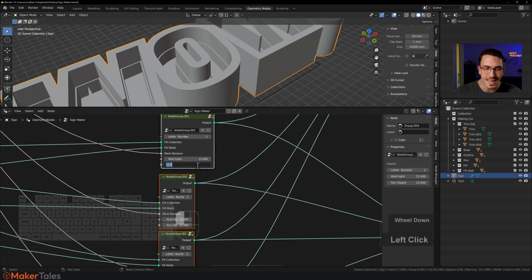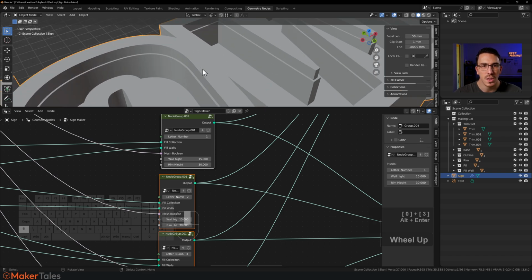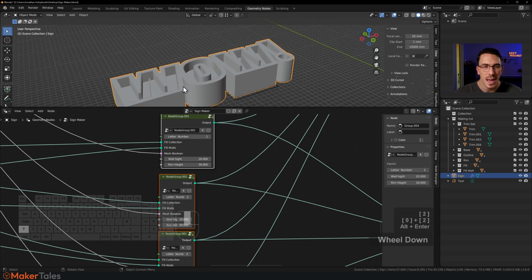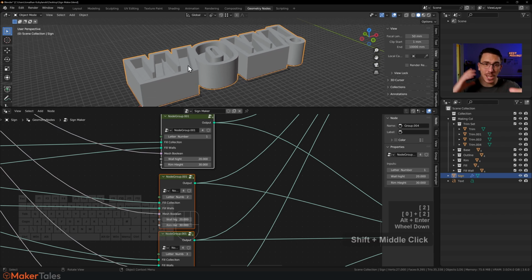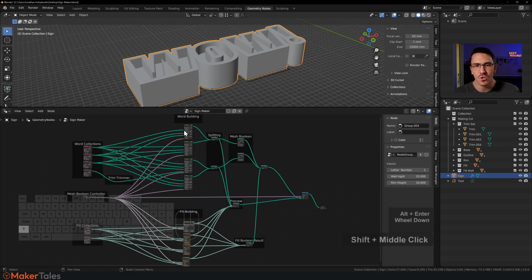The rim height now is 30. Hold down Alt, click, that brings up the rim height. Oh, but look, the rim wall height also needs to go up. I'm pretty sure it needs to go up by 5. So I'll type in 20, Alt, Enter. There we go. And now we've just made this much thicker. You can edit this to your heart's content, however you're wanting. But let's say that there is exactly what I'm wanting. I'm wanting to keep it with this trim in place.